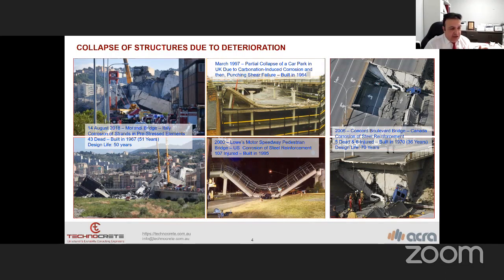When we are designing a structure, we have to provide a package of structural design and durability design. Otherwise, we will face premature deterioration if we only focus on the structural design based on the standards which we have. Our standards are mostly prescriptive-based standards, and we cannot rely on the outcome of those standard parameters if we consider them for the durability performance of the structure in that environment.